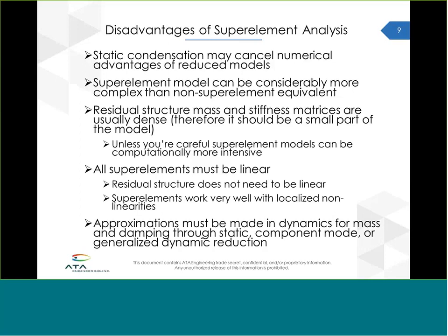The residual structure, so what you're left with after all the reductions have been created and the models are assembled before solving for the system, that mass and stiffness are generally pretty dense. For a normal type of structure, usually those matrices are very large but very sparse. With superelements, those matrices are generally smaller but more dense. So that, again, can cancel out the computational advantage.